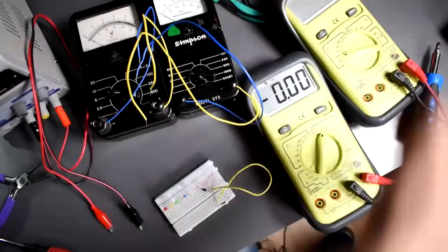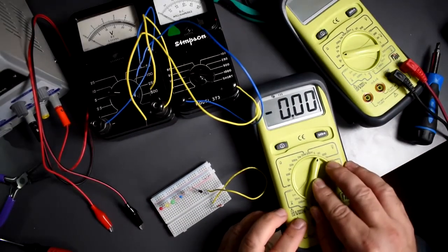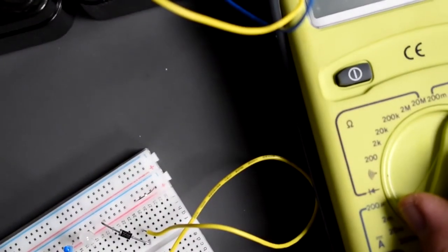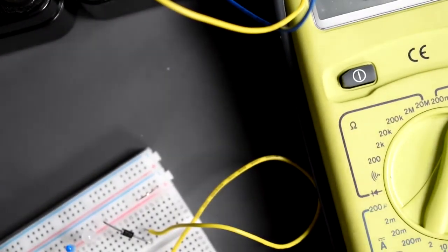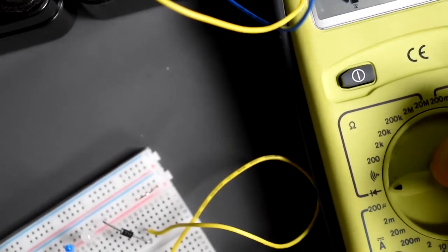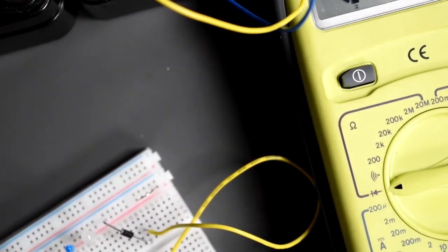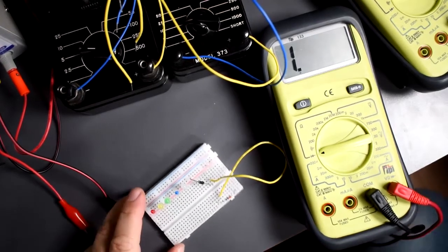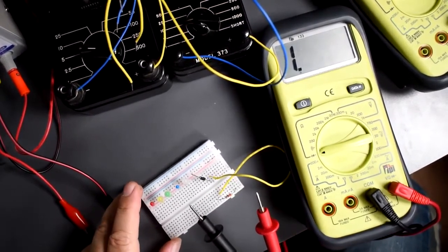So we have a few diodes here. Now, let's turn on the meter. Let's make this meter a continuity diode tester. So it's this little symbol here. Here is a diode tester right here. It shows a symbol of a diode. Okay, so let's just turn the dial onto the diode tester. Okay, so in the description of how things work, this should tell us the forward bias voltage of the diode if we polarize the diode properly.